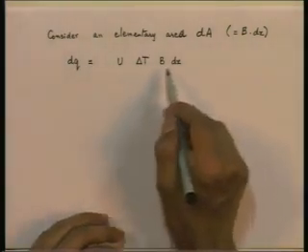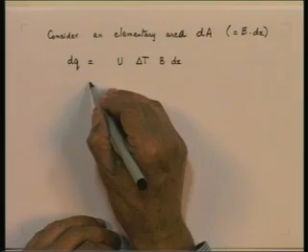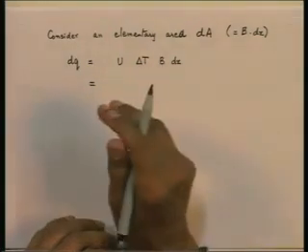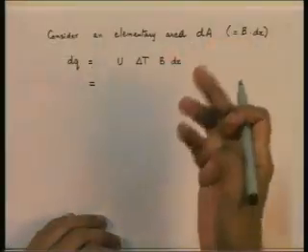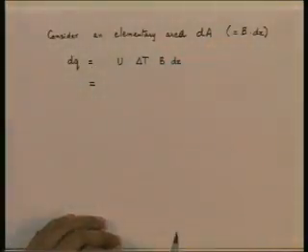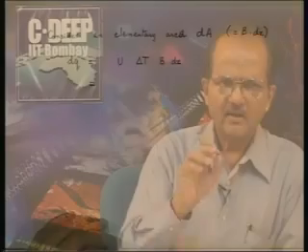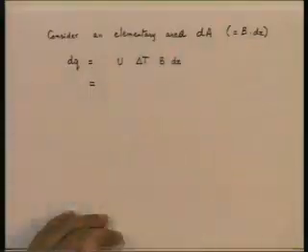Now, because this heat transfer takes place from the hot side to the cold side, the enthalpy of the hot side fluid decreases by this amount, and the enthalpy of the cold fluid increases by this amount. The enthalpy decrease of the hot fluid is seen by the decrease in temperature. So, over the length dx, the temperature of the hot fluid decreases by dTh.